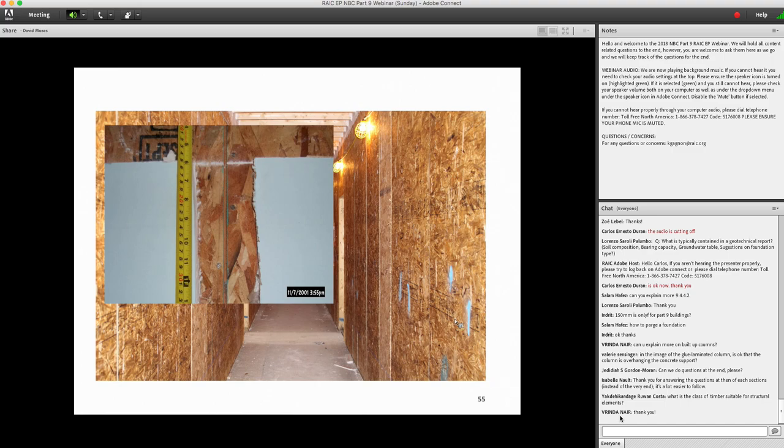But you can see that there really wasn't a lot of attention paid to the spacing between the nails here. On the left panel, we only see one nail. Just point to it here. And on the right panel, we see two nails at a different spacing, and we don't really know where the next nail is. So a little more attention to detail by the builders would have been better in this case.